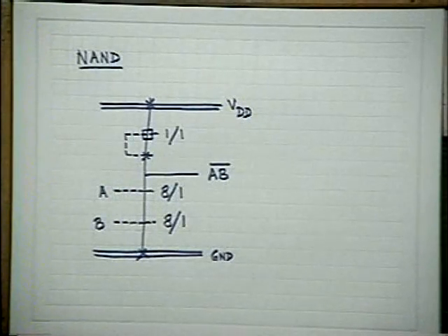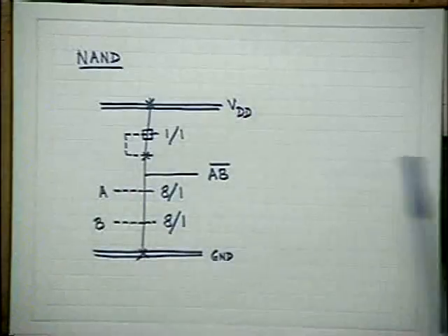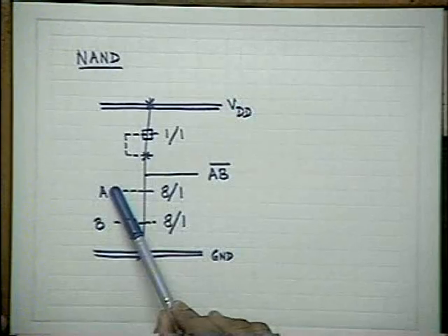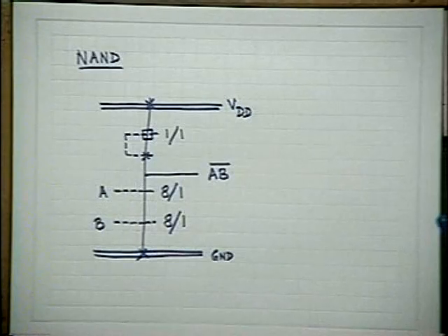If you want to realize NOR from TTL, it becomes more complicated. Can you tell me, suppose one input is floating, is it equivalent to 1 or 0 for TTL? 1. Whereas for this case? 0, because you are not applying any voltage. Of course, if there is pickup, you will have a problem. But if it is very properly screened, and you have kept it floating, this transistor remains off. Only by applying a voltage, you turn it on. That's the basic thing of nMOS.